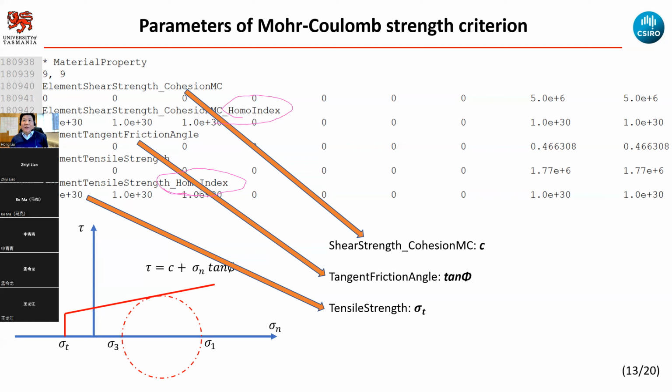Okay, if I give this value as an extremely big value, then in that case, I have a number of cohesive elements, or triangle elements, here. If I give a value which is quite big, that means all of the cohesive elements are given the same value as this one.